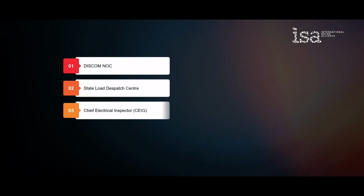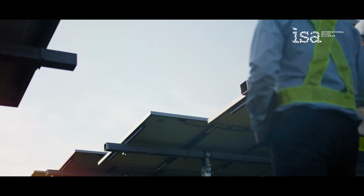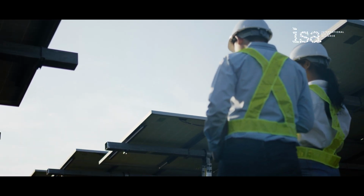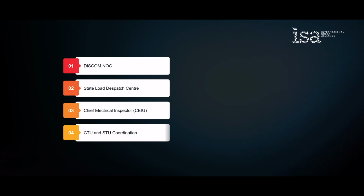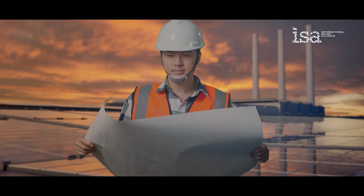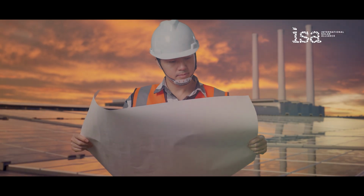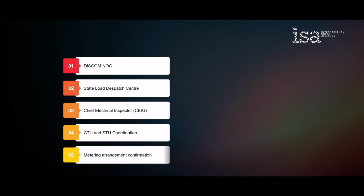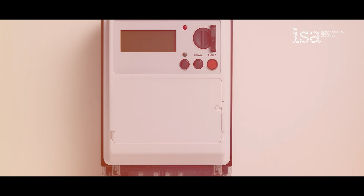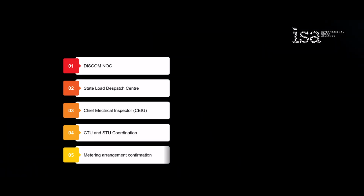Chief Electrical Inspector, CEIG, a mandatory safety and electrical standards compliance check that is critical before commissioning to ensure the electrical systems meet all safety norms. CTU and STU coordination, necessary for transmission and evacuation planning to ensure efficient power transfer from the plant to the grid. Metering arrangement confirmation. Confirmation is needed on the type of meter, for example ABT meter, to be used for measurement and billing at the point of connection.